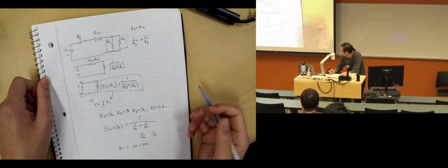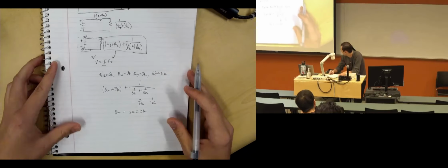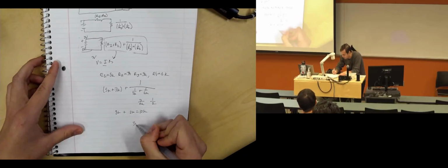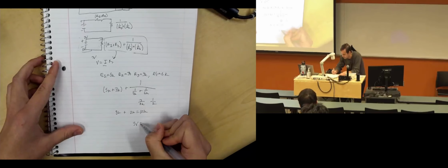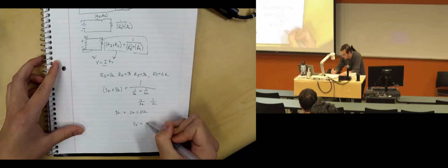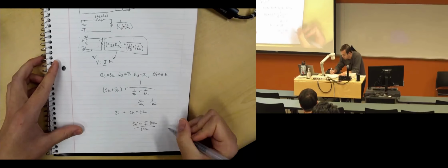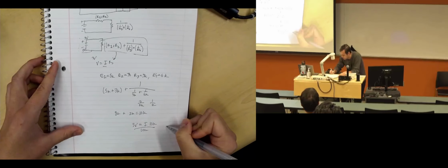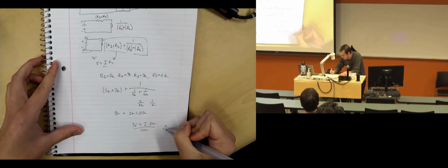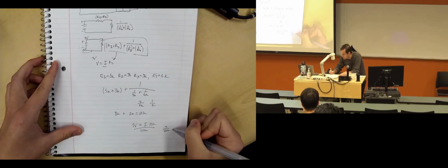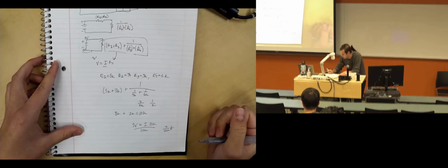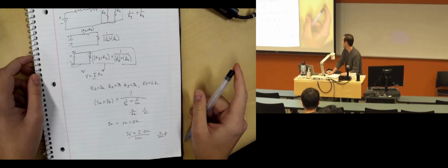And then we use the V equals IR that I was talking about before. So we have 3 volts. I think I said 5 in the other one, but it's fine. 3 volts equals I times 10K, divide both sides by 10K. So you have 3 over 10K amps, which is really small. So your circuit would be just fine.